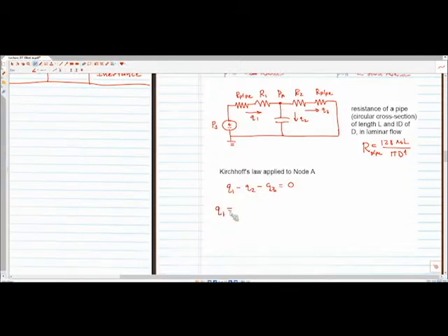All right, so Q1, we can look at this in terms of Ohm's law, which is basically the current running through a resistor. So we have V is equal to IR, or I is equal to V over R. So the potential drop over this left leg here is going to be PS minus PA. And then we have resistance of our pipe, I'll just make it RP to make it shorter, and R1, because these two resistors are in series.